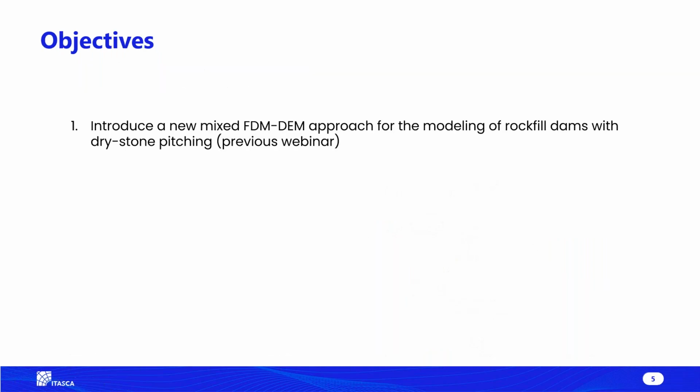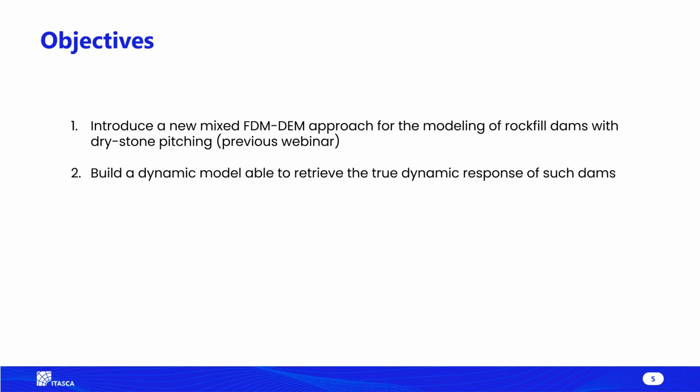The main objectives of this part of our study are, first, to introduce a new mixed FDM-DEM approach, a coupled continuum and discrete element method approach, for the modeling of such rockfill dams with drystone pitching. By the way, this part of the study was presented in a previous webinar last year. For this webinar, the main objective is to build a dynamic model which is able to retrieve the truly dynamic and seismic response of such dams. And finally, to evaluate and quantify the dynamic resistance of such dams.